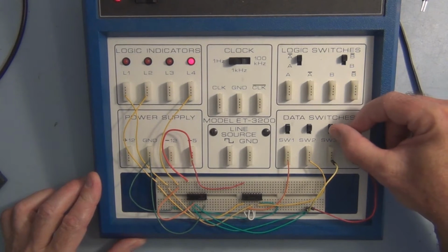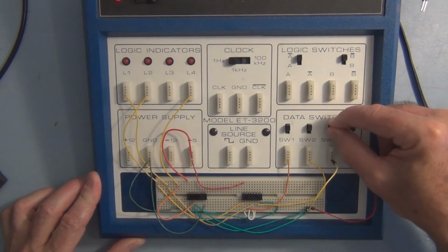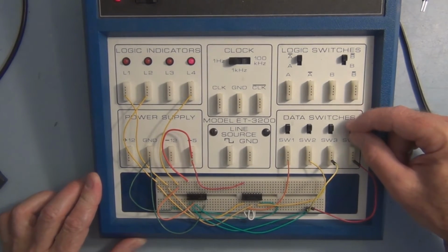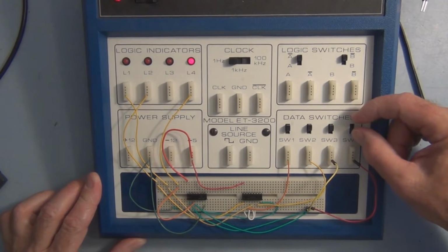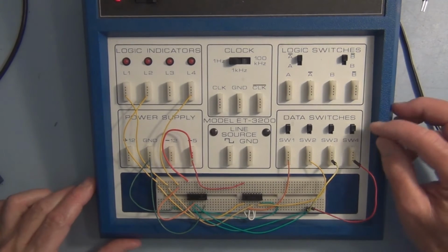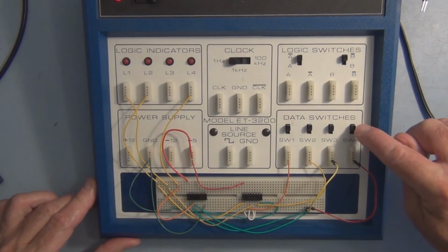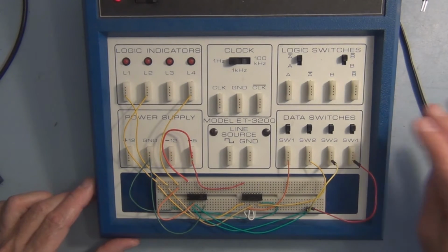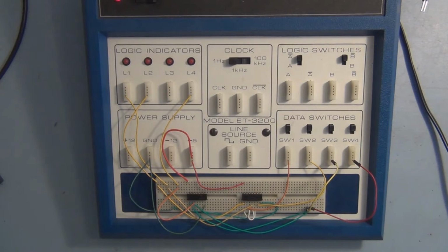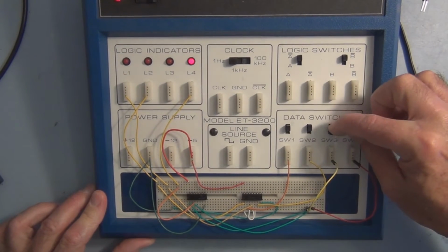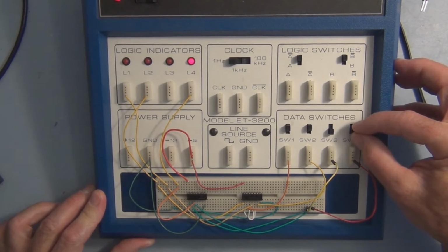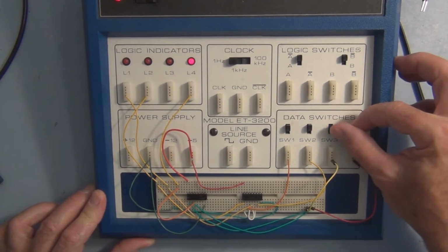And you can see that as soon as I change one of the inputs, the LED lights or turns off. And that decision is based on the value of the inputs at that instant of time. It's not being based on something that's being stored that occurred in the past. That's a combinatorial logic circuit. Very simple one, but that fits the definition of a combinatorial logic circuit.